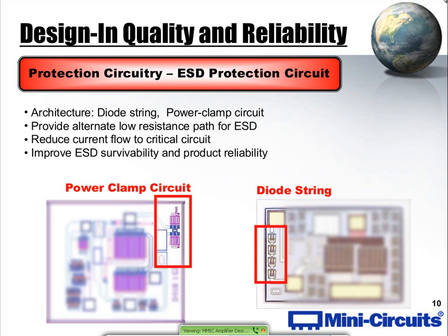The most critical, or the most sensitive parts that we make, and everyone in the market is making in gallium arsenide today, are the PHEMT structures. The gate structure is more fragile than, let's say, the junctions on a bipolar design or an HBT approach. And in order to get those gate structures as robust as possible, we will embed on all of the ports, whether they're active ports, RF ports, or even passive ports on the device, which can be exposed to the customer, protection diodes.